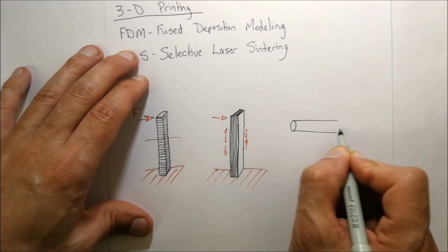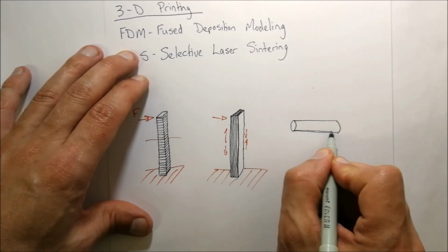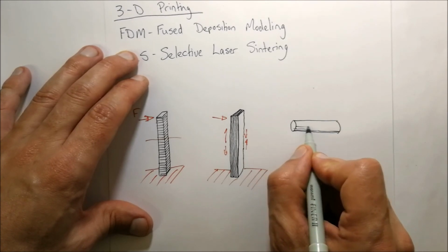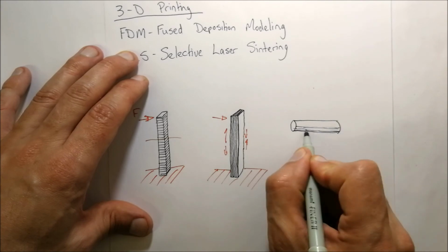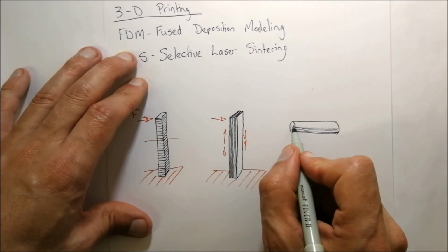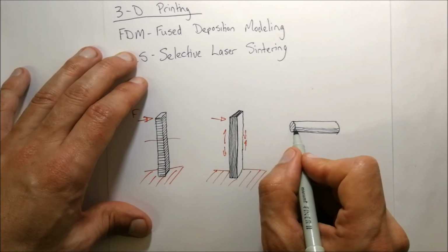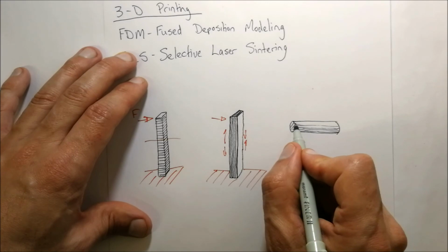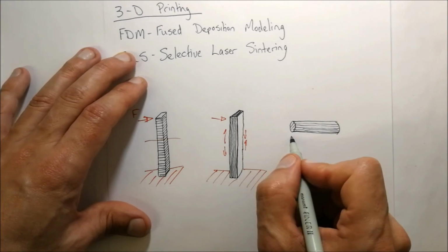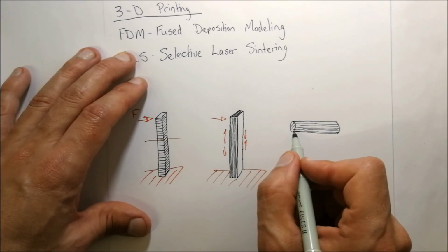as in this fashion, the printing of the bottom layers is going to be fine, and then maybe the printing of the side layers is going to be fine. But what's going to happen when it comes to printing the material at the top? Often you need to have supporting material over here so that the printing is possible on the top. Otherwise the material will just fall down into this cavity. And then the supporting material needs to actually be removed.